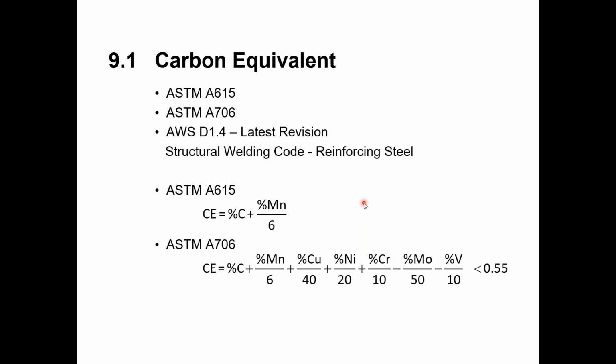The reason those preheat requirements exist is to prevent the embrittlement of the steel from rapid thermal shock, an increase in the temperature from the welding procedure, or a rapid decrease in the temperature from a localized temperature of the welding if you're in a cold environment.